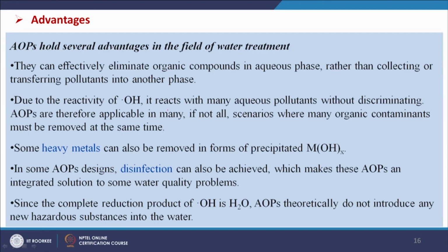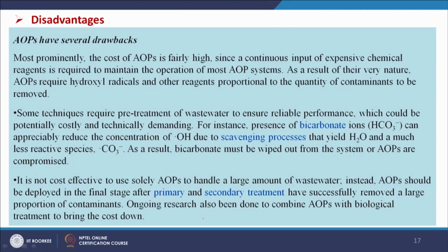Due to the reactivity of OH dot, it reacts with many aqueous pollutants without discriminating, and AOPs are therefore applicable in many if not all scenarios where many organic contaminants must be removed at the same time. Some heavy metals can also be removed in the form of precipitate, and in some AOP designs disinfection can also be achieved, which makes these AOPs an integrated solution to some water quality problems. And since the complete reduction product of OH dot is H2O, AOPs theoretically do not introduce any new hazardous substances into the water. So, these are the advantages.